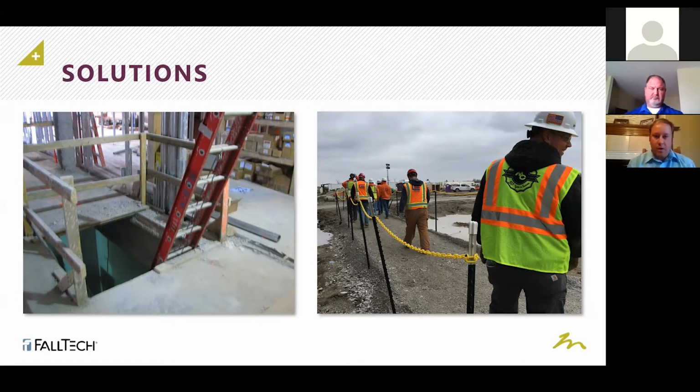Let's take this common example on a job site right to the left here. We transition from one level to another level with an extension ladder. And while this is in compliance with the regulation, there still is a potential for someone to fall walking by that ladder or accessing that ladder. And so a simple solution is what they would call an offset rail, or essentially an L-shaped rail, so that it protects that opening. And again, it's thinking beyond the compliance side of things and really looking at the hazards and trying to prevent people from getting themselves in trouble or making a bad decision.